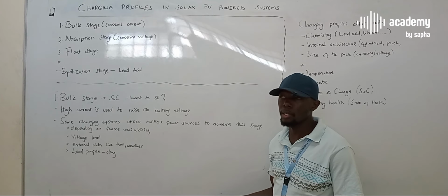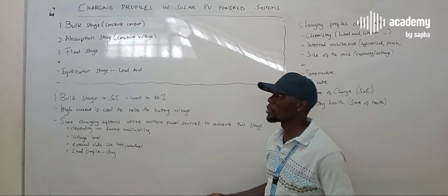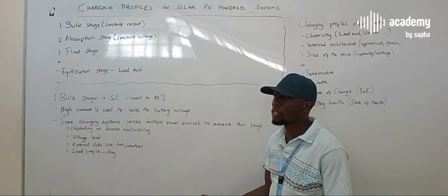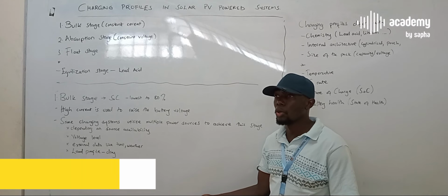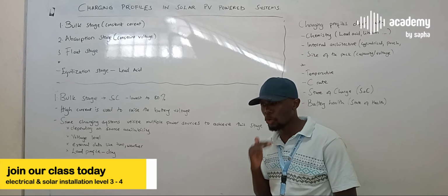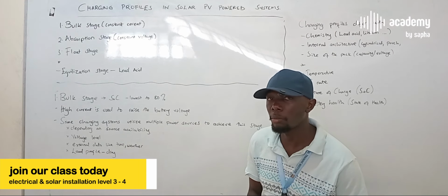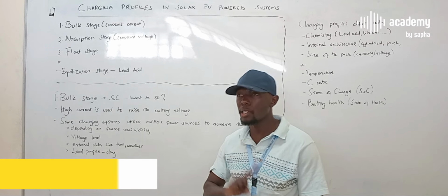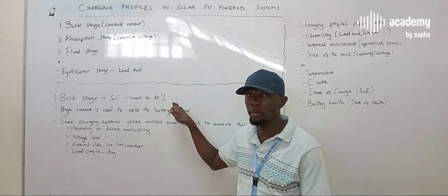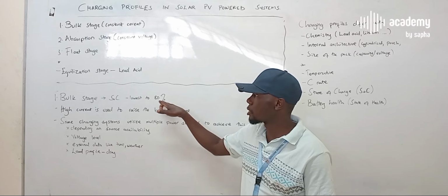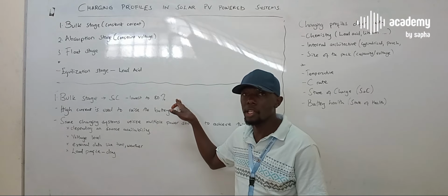If you size the system well, for example in lead acid, the lowest will be around 50 or 60% state of charge. So the bulk stage normally happens from the lowest point of the battery pack, raising the SOC to around 80 or 90%, depending on the battery type. In most cases it's 80, in some cases it's 90%.